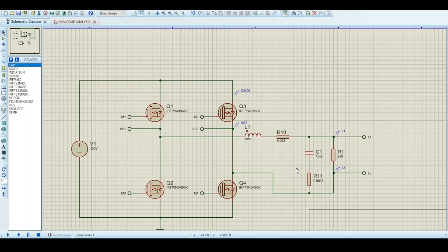And anyway, in reality, you do not want to deal with perfect components. You sort of want some parasitic resistance. It helps with damping as well. And over here I basically have a 200 ohm load, and I'm going to link a video in the description where it talks about designing an LC filter.